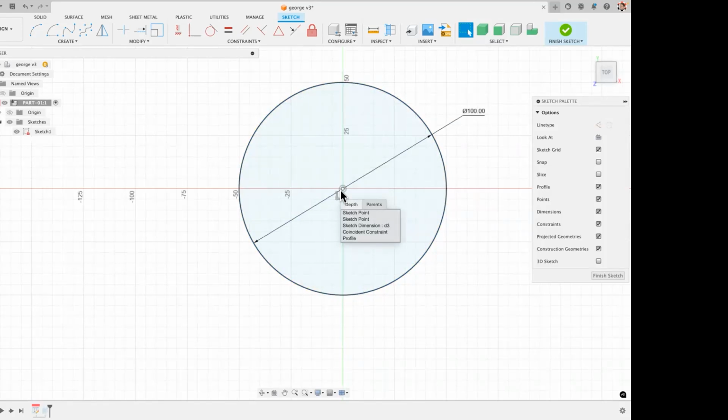Okay. And it gives me, I have a constraint. Did you remove the constraint? No, no, no. You might have been a little over to the side. If you're off to the side, you get something else. It was close enough to the center point, but also close enough to the constraint. Now I have the constraint in my list. If I'm directly over this circle, it's not going to find that constraint because I'm not close enough to it.